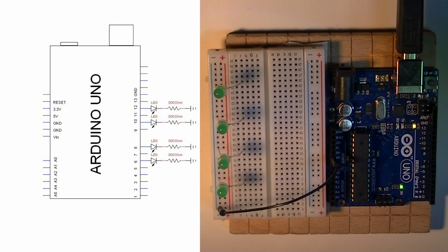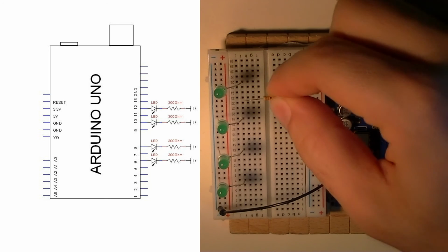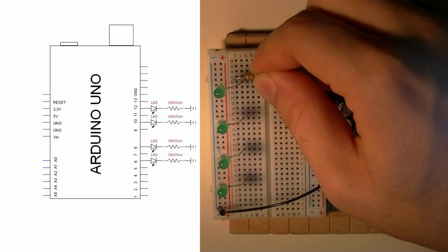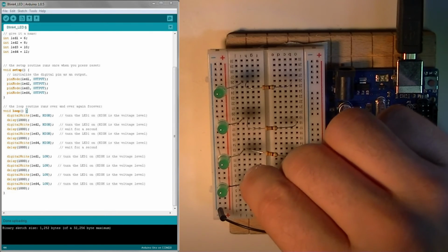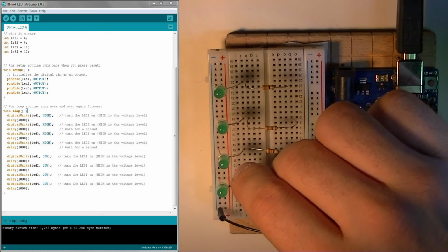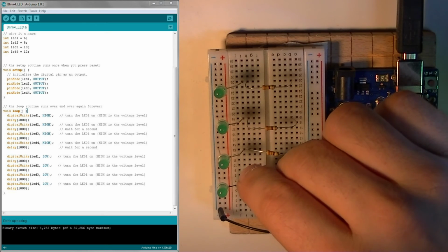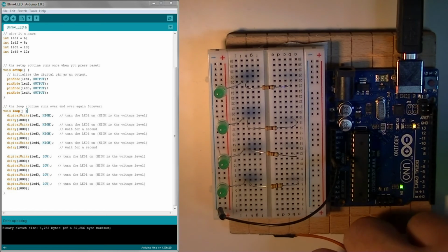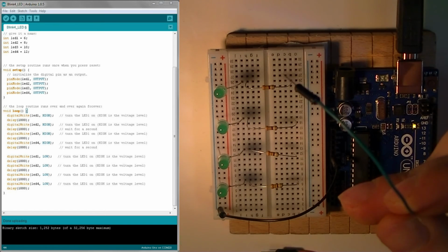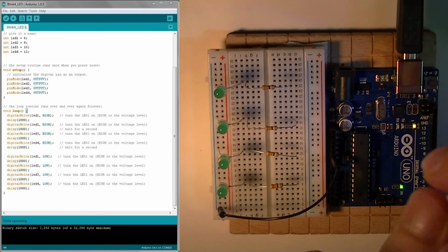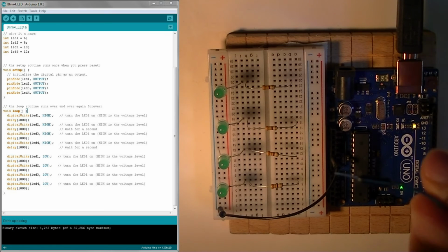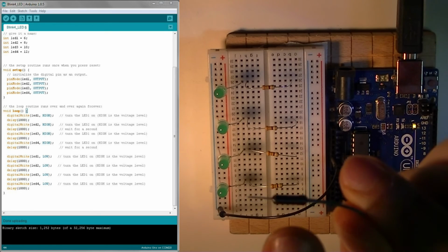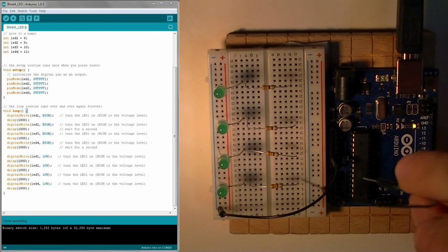And now LEDs, as usual, are connected to a resistor before being powered by our pin outputs, which I think are 5 volts. So now, as you can see in the program, we're using 4 outputs. I think I've selected pins 6, 8, 10, and 12, and the reason why is because these breadboard wires are a little bit wide in this section, so it's much easier to plug them in if they're not right next to each other. But even if they are right next to each other, they'll still jam somehow.